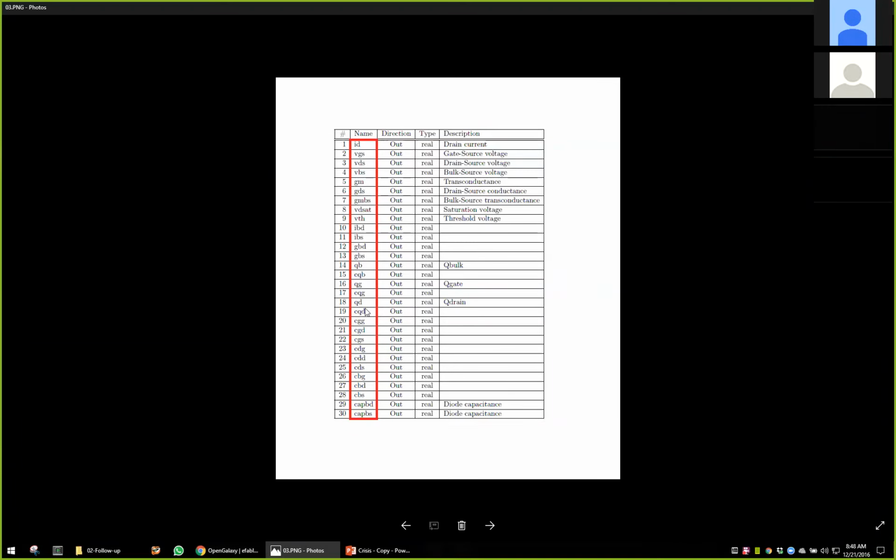So let's say when you're doing like 0 to 1, and if you want to see what's the charge leakage at the drain, you can individually plot the charge to look at the charge leakage. This is something which can give you an intuitive sense of what the leakage looks like or what the VTH variation is when you are sweeping the temperature.